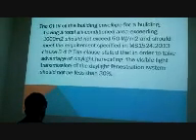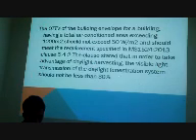The OTTV of the building envelope for a building having a total air conditioned area exceeding 1000 meters squared should not exceed 50 W/m² and should meet the requirements specified in MS 1525:2013 clause 5.4.2. The clause states that to take advantage of daylight harvesting, the visible light transmission of the daylight fenestration system should not be less than 50%.